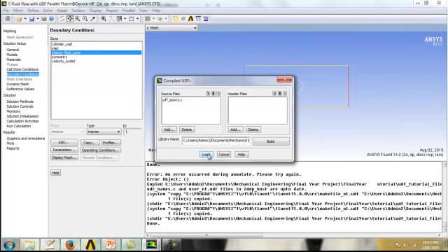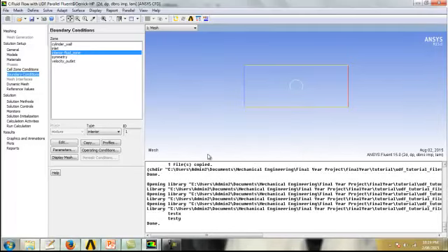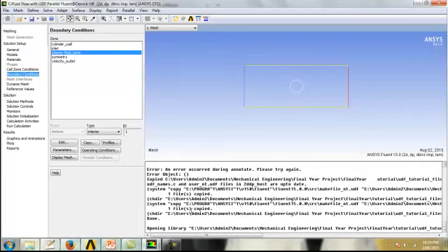And then you need to load your DLL. So if you're familiar with C, you'll know what that does. If you're not, it doesn't matter. You just need to know that you need to do that. And now you can see the two user-defined function names popping up, which should happen if everything went well. If something didn't go well, there'll be an error, and it will tell you which line is wrong, which is quite handy.